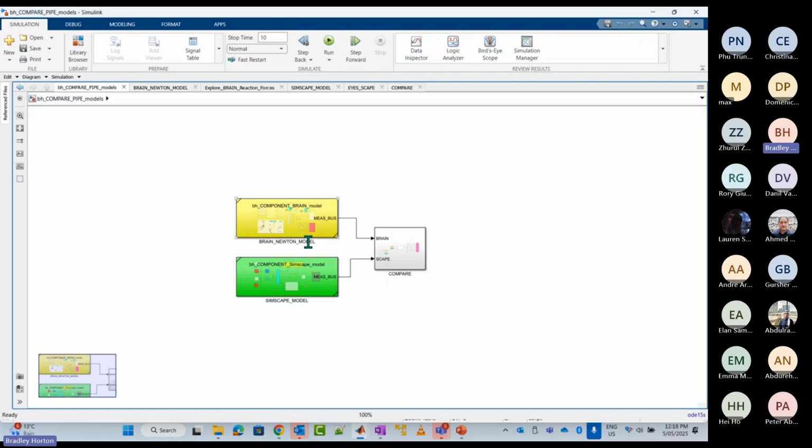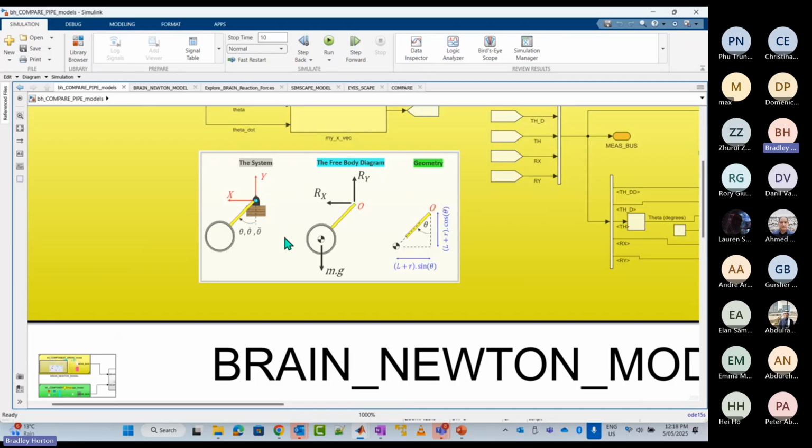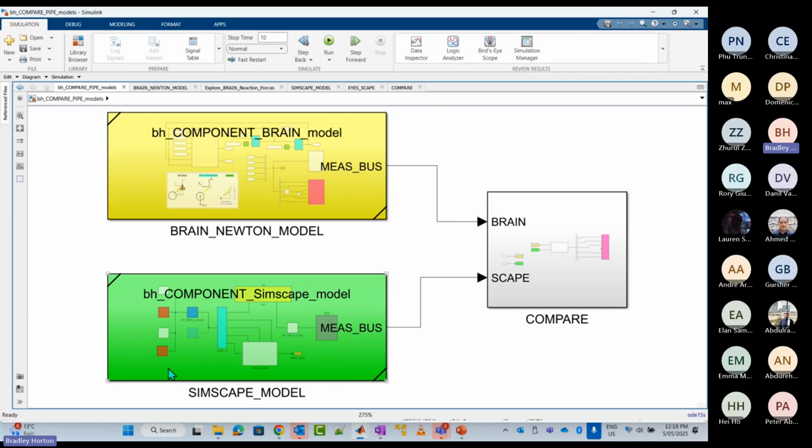If you open this Simulink file and it looked like you were staring at it from 10,000 feet above the ground, or alternatively, if the file opened and you've got your face pressed against the screen, neither of which are satisfactory, then the way to make the model occupy full screen is to click anywhere in the white canvas of the Simulink file, and then hit the spacebar key on your keyboard, and that should make everything fit nicely into full screen view.